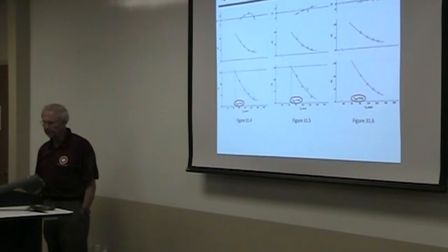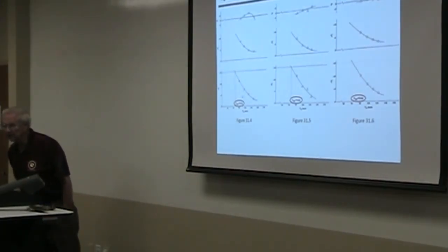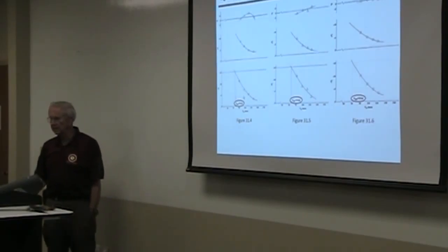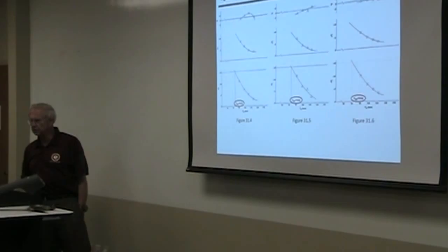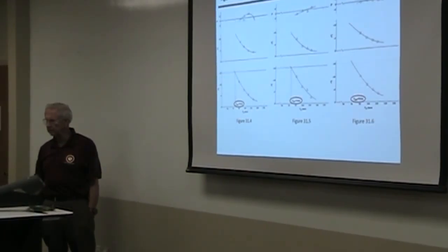Well, notice that comes out to a VMC of, on this airplane, which was a Cessna 310, about 78 knots for this condition. Okay. And then we try another altitude, and we do the same thing. Three different altitudes we've done here. Again, side slip.